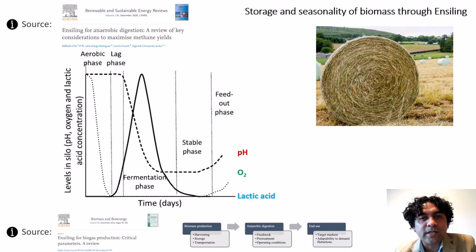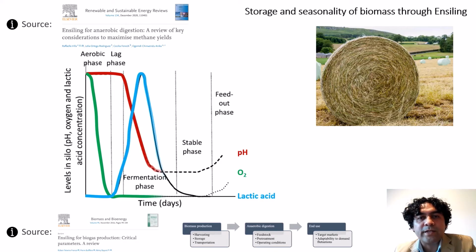Once oxygen has been depleted, the microorganisms capable of anaerobic growth, for instance lactic acid bacteria, enterobacteria, clostridia, and yeast, begin to proliferate and compete for the available organic matter. During the stabilization phase, the anaerobic conditions are maintained with a decreasing fermentative activity. The pH remains stable, wherein minimal enzymatic and microbial activity will occur until the silo is opened again. After opening the silo for biodigester feeding, aerobic microorganisms are reactivated, which may lead to energy losses. Thus, the feed-out should be quickly carried out.